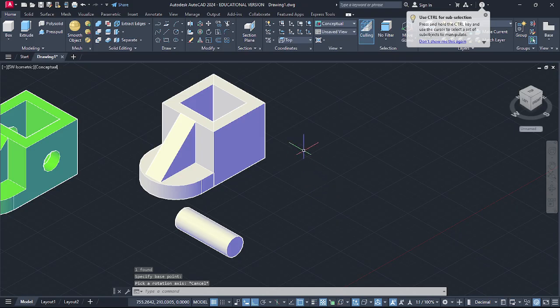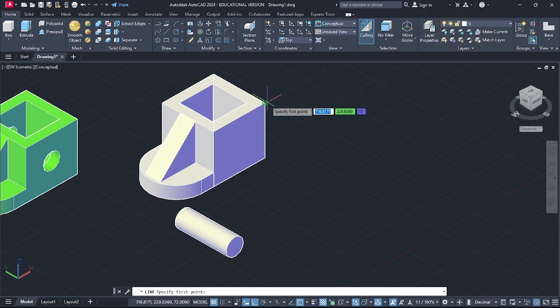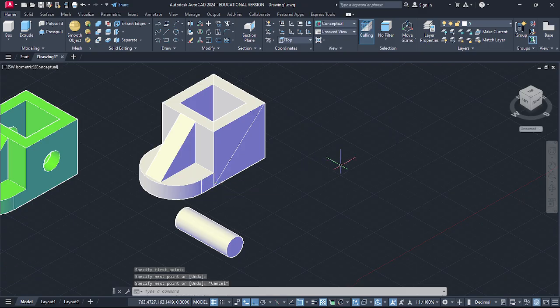Okay. Here also you have to use a diagonal line, here to here. Make one diagonal line. It is useful for move and Boolean operations. So select the move command, select the cylinder, enter.